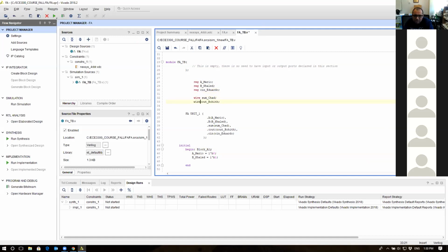I flipped them. Because you cannot push that value into a wire, unless you do something. Wait, there's a way to do it. It's called force and release. There is something in the test bench called force and release, so you force a value inside the wire.